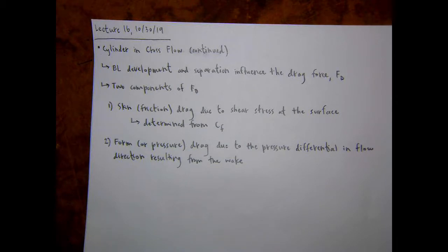And if you had, say, a cylinder that was floating and wasn't fixed, and you had a pressure differential, it would be pushed one direction, right? It would be pushed in the direction of lower pressure. But because we're talking about a fixed object, we have this pressure differential that's maintained in the flow, and so instead of moving the object, it's exerting an extra drag force. So that's how that pressure difference shakes out.